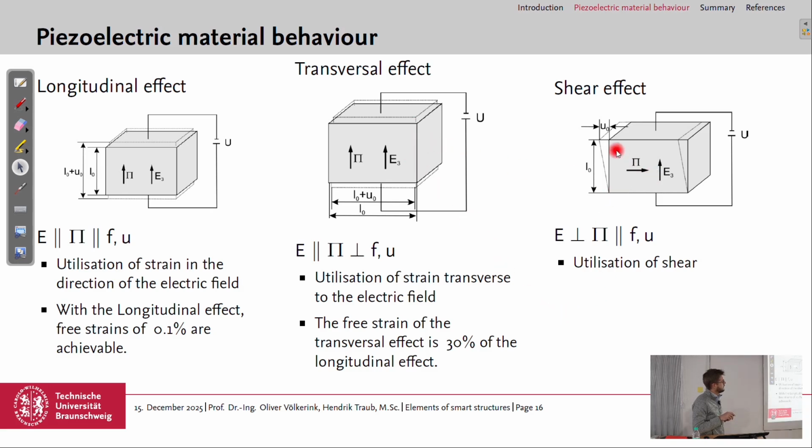And then the piezoceramic would be sheared, and we can use the displacement in this direction, so parallel to the polarization, and utilize shear. There are also some actuators that use this effect, but we mainly focus on the longitudinal and on the transversal effect.